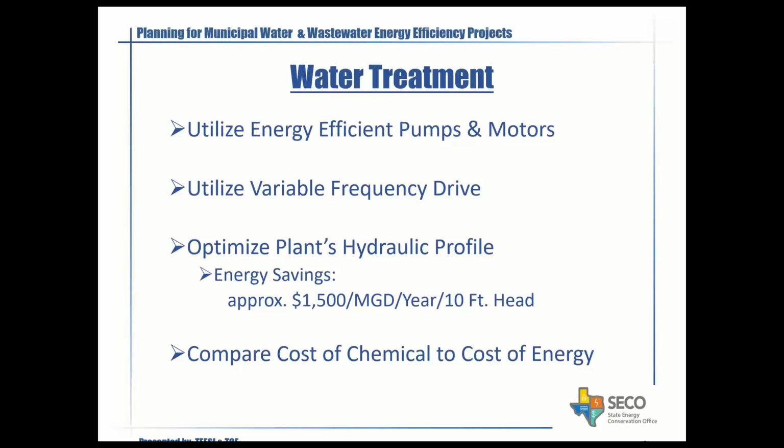For water treatment, we look at the utilization of high efficient pumps and motors. We look at utilization of variable frequency drives for motors that operate over a range of flows and have to turn on and off. We look at optimizing the plant's hydraulic profile so that you don't have little intermittent pump stations within your plant. And we look at your cost of chemical and compare the cost of chemical to the cost of energy to see if there's any relationships that we can see in your operation and maintenance.